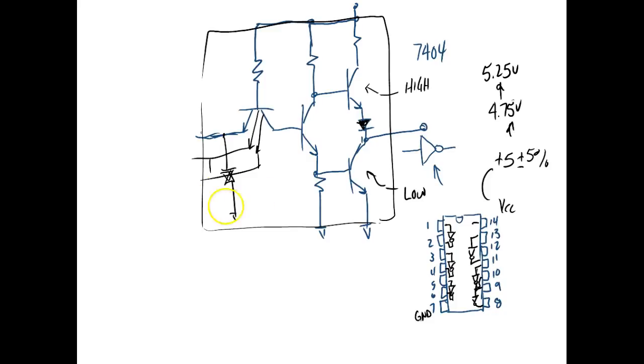But what I want you to know is we input on transistors, we output on transistors. So this is why this is called transistor logic. So DTL, what would that mean? Well, it means we input on diodes and we output on transistors. And that was a phase we went through. RTL was a phase they went through, where they input on resistors and output on transistors.